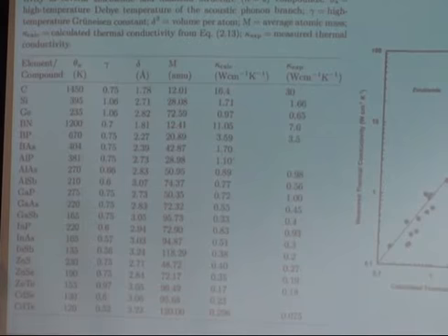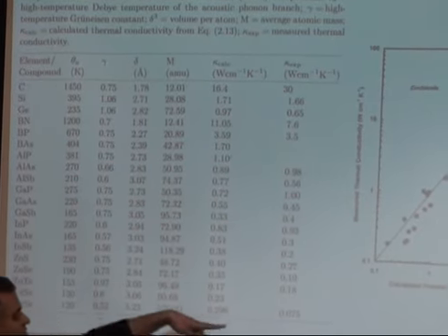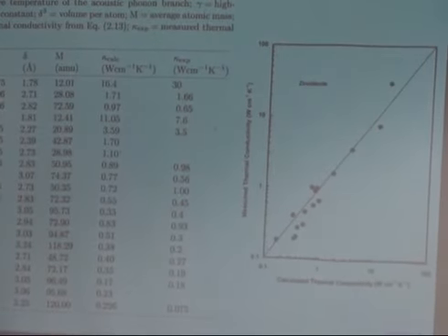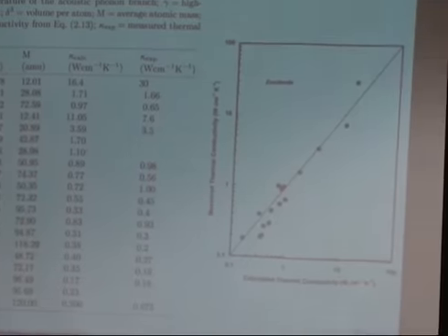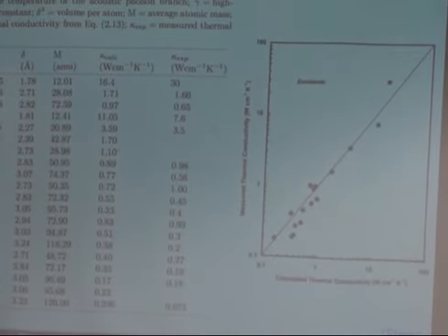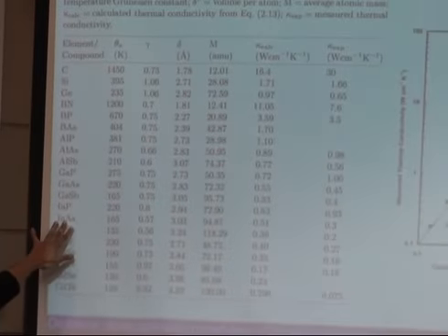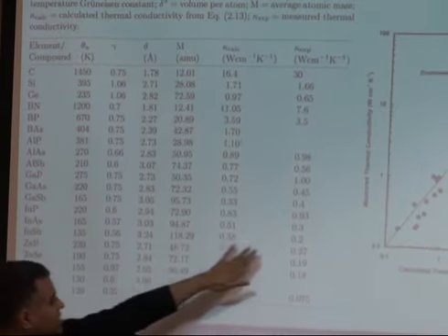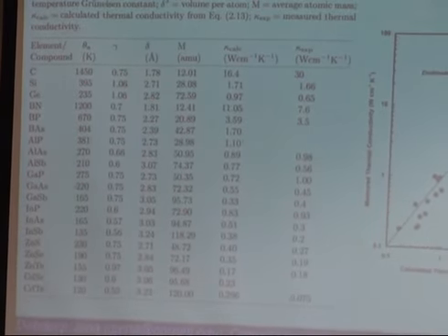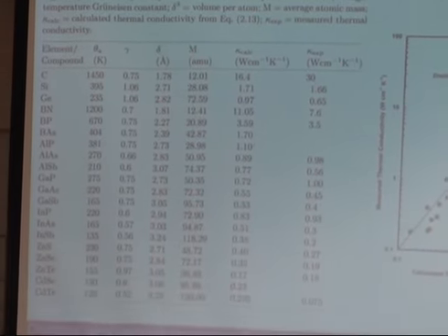And coming down, cadmium telluride, a II-VI material. This is 0.075. This is very low. So you're really spanning almost 2 orders, actually more than that, 3 or 4 orders almost, right, of thermal conductivities here. Indium arsenide, which is a very high mobility semiconductor, 0.3 or so watts per centimeter Kelvin, right? So that's experimental, and then there are some calculated values as well.